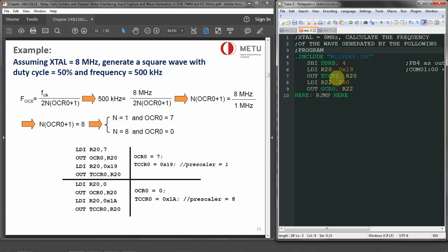So if we want to generate the wave, we have to count up to 200, and to go down, we need one more clock, which is going to be 201 in this case, and count up to 200 again and go down +1, 201, and so on.